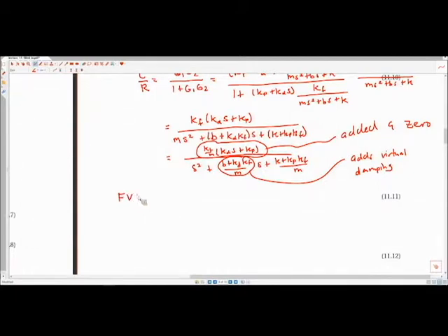Okay, so assuming that you've built a controller that is stable, which we're always going to be doing first, make sure it's stable, we can look at the limit of time going to infinity of C of t equals the limit s to 0 of s C of s, right?